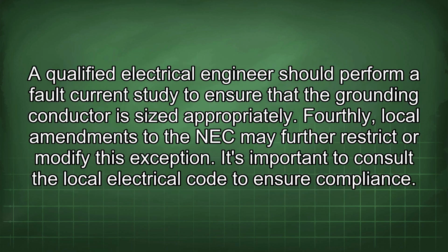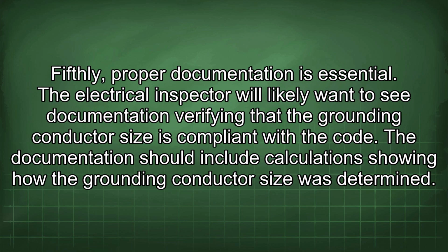A qualified electrical engineer should perform a fault current study to ensure that the grounding conductor is sized appropriately. Fourthly, local amendments to the NEC may further restrict or modify this exception. It's important to consult the local electrical code to ensure compliance. Fifthly, proper documentation is essential. The electrical inspector will likely want to see documentation verifying that the grounding conductor size is compliant with the code. The documentation should include calculations showing how the grounding conductor size was determined.